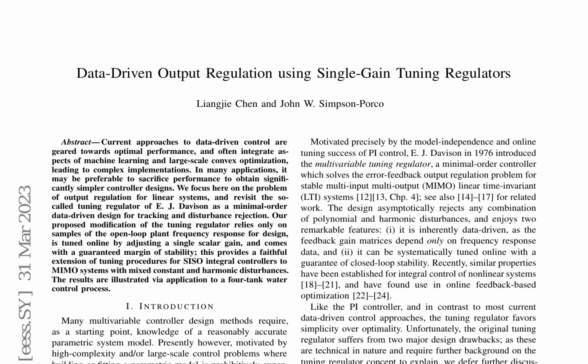The authors delve into the analysis of the closed-loop system matrix A, in terms of its low-gain Hurwitz stability. They introduce a reduction lemma that allows them to focus on the low-gain stability of the matrix A_RD equals G_L, F. The authors also define low-gain stabilizability for a pair (A, B), which is characterized by the existence of a feedback K such that A + BK is low-gain Hurwitz stable. The authors then prove that the pair G is low-gain stabilizable due to its controllability and the fact that all eigenvalues of A lie on the imaginary axis.